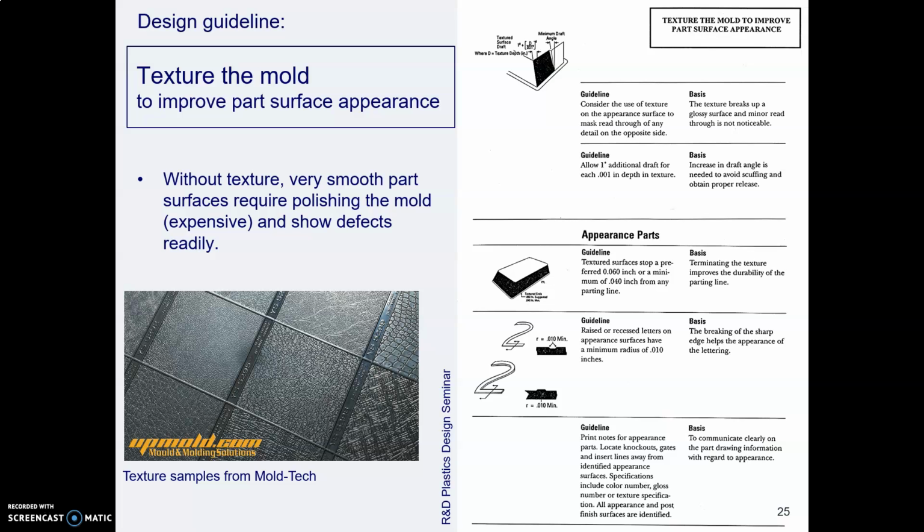They get polished because after a certain amount of parts being made, there are wear marks inside the mold cavity and you don't have a smooth plastic part anymore. So you have to take your mold cavity, you ship it. Used to be you ship it, if you're in Oregon, you ship it to California and get it polished, and it costs a lot of money.